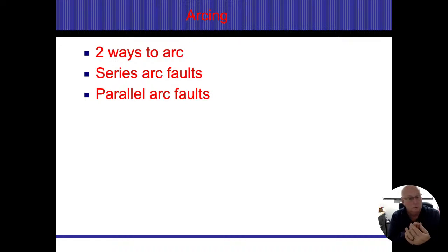Now, if it's bare bones metal on metal, then we're going to have an unlimited flow of electricity, and most likely my breaker will trip. But before I get to that point, I might just have a breakdown in insulation. So I might only have 20 amps on a 20 amp breaker that's jumping across these things, and it's constantly making sparks. And then all of a sudden it actually ignites the insulation. Or if it sparks and gets to an opening in a junction box or an electrical panel, then that could get to the wood structures of the properties.